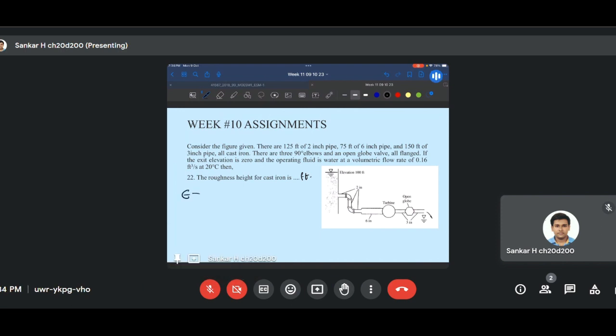And if we go to, as mentioned earlier, page 381 of the book on fluid mechanics by Frank White, you'll find the epsilon value to be equal to 0.00085 in feet, and this value in millimeter is what we wrote earlier as 0.26 millimeter.